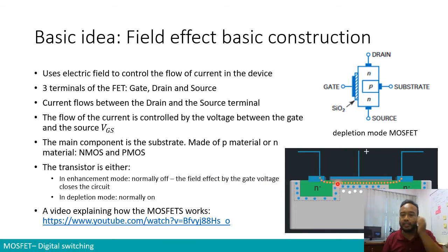Enhancement mode is when you have what we call the channel over here. The N channel over here is not there. So by applying the voltage, you create the channel. So the more voltage you put, the larger the channel will be. So that's what we call enhancement mode.